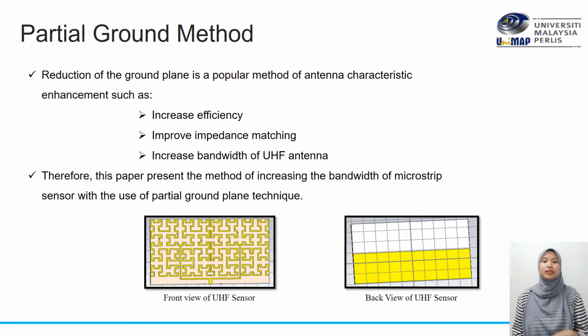such as to increase the efficiency and improve the impedance matching, and the focus of the paper is to increase the bandwidth of the UHF antenna by using this partial ground technique. And we can see how the partial ground looks from the back view of the UHF sensor.